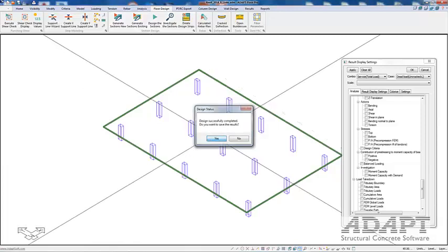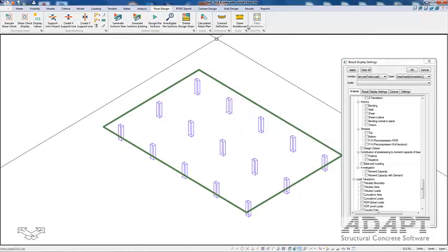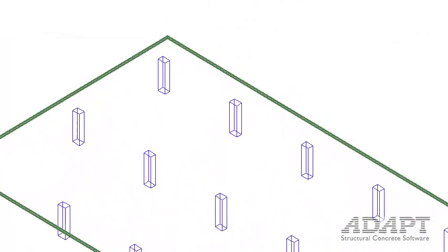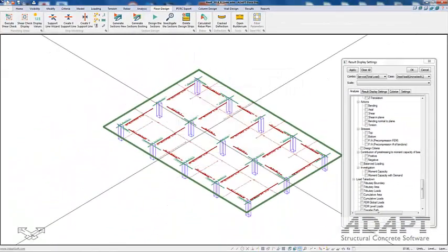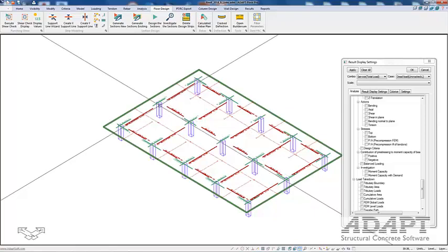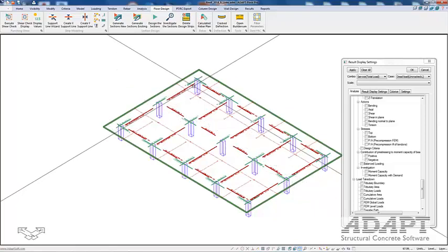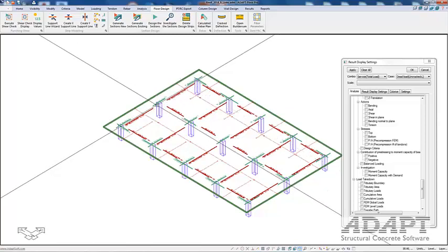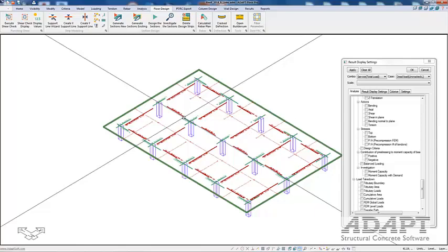We'll select yes to save the design. And now we have reinforcement that we can produce graphically on screen. So I'll just select the option to calculate the rebar plan for the envelope of the combinations. And you can see that we have reinforcement. Green represents the top reinforcement, red represents the bottom. Green is isolated or grouped rebar, and the bottom rebar is distributed.